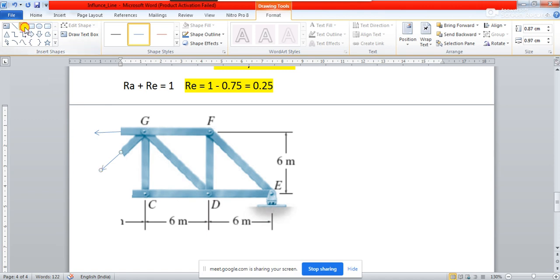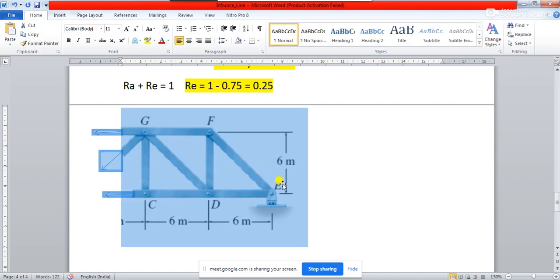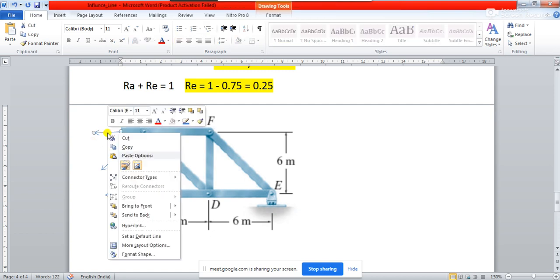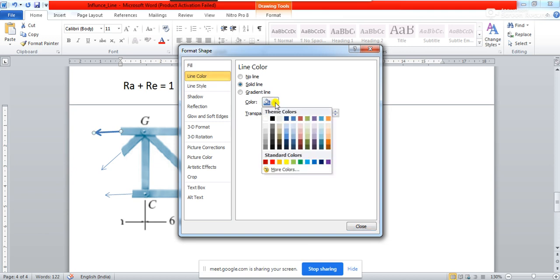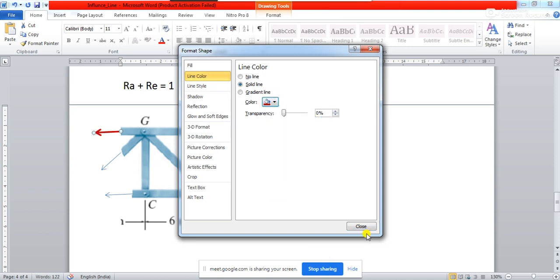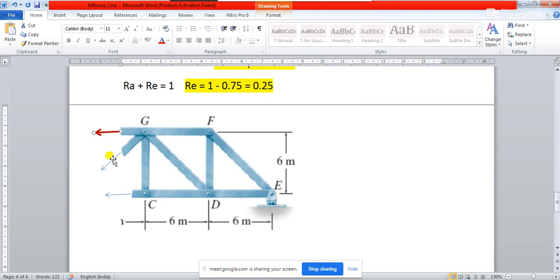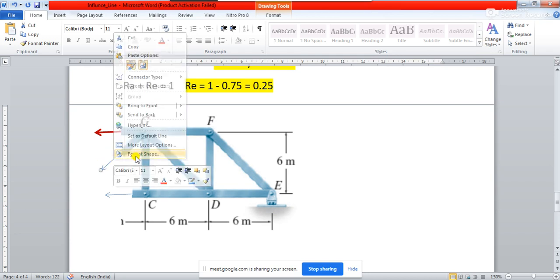All arrows, you see, we are taking outward direction. You don't worry about it. If in this outward direction you are getting a positive value after calculation, then your direction assumption is correct. Otherwise the direction of the force will just be reversed. Okay. So that is how we generally do, right?